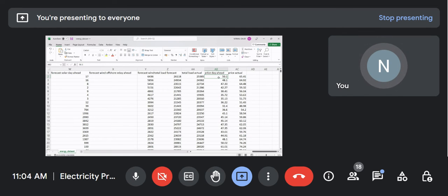With all these projected and actual parameters which we have noted down here for that particular day, for that particular hour, whatever the consumption and whatever the generation that happened, this is the price ahead which we quoted, but the actual price came to be 65.41. Am I right, sir? Now here, if you have a shortage, the price expected was 50, whatever the currency, but the actual price during this time has gone to 65. So if you had some shortfall, you would have to buy at 65, not 50.